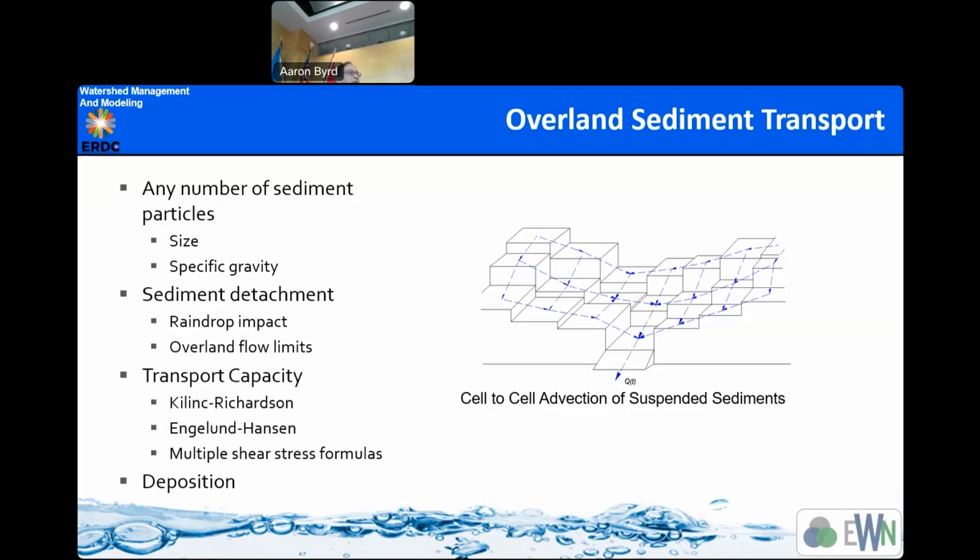The overland flow limit is if the shear stress is bigger than the critical shear stress, then the sediment starts to trigger from that point. And transport capacity is nothing but to see if the amount of sediment load at a particular grid cell, the overall energy is able to transport that or not. Even if the source is available, if the transport capacity or energy isn't there to transport that from one grid cell to another, then it doesn't take all with the flux.